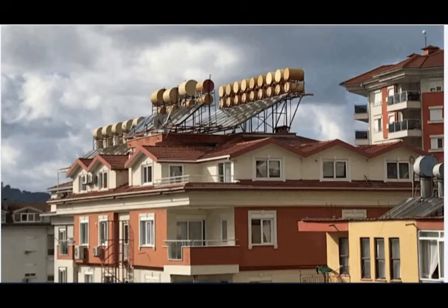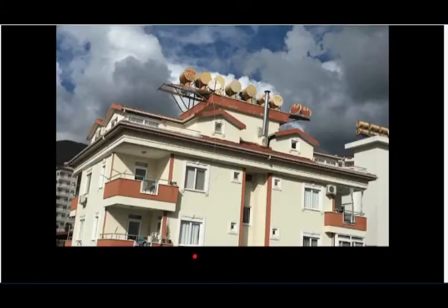Roof plan. Let's check the details one by one again, the requirements that are supposed to be in the roof. Do you remember that we asked you about the console? Let's go back. For example, we asked that you can go a maximum of 80 centimeters as a console. Here you can see that they have done exactly 80 centimeters.